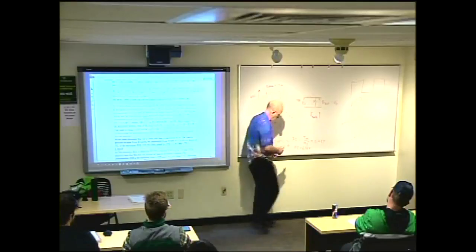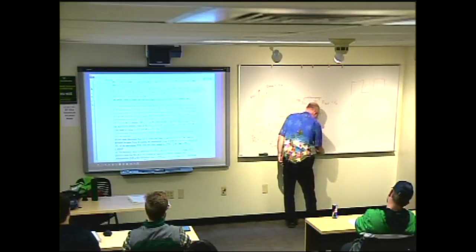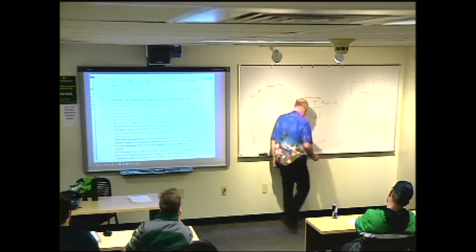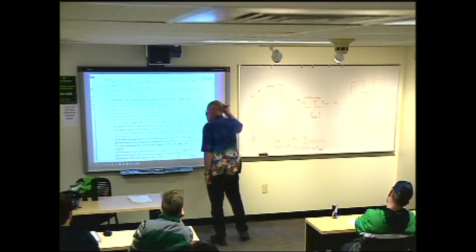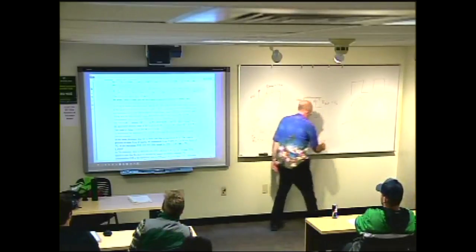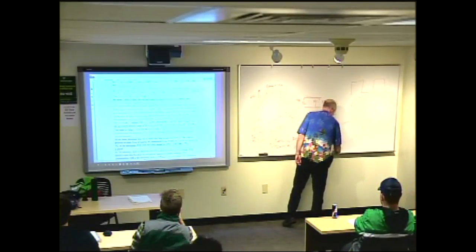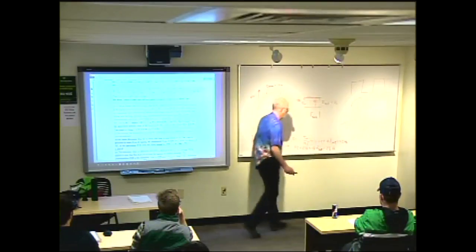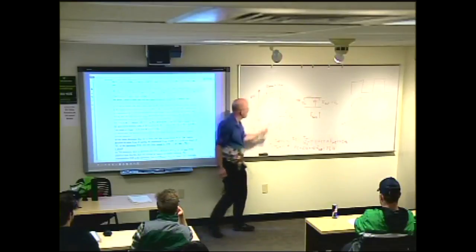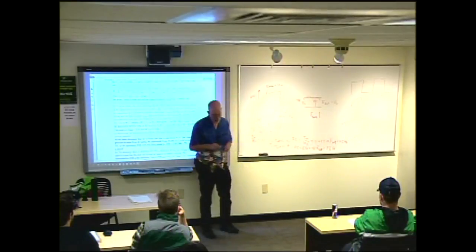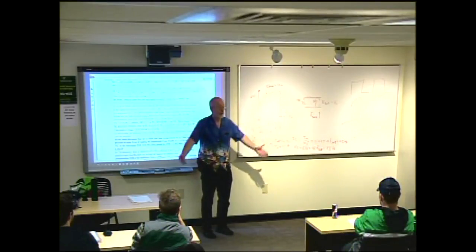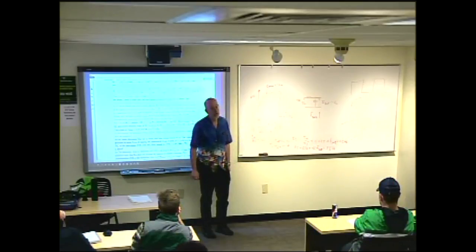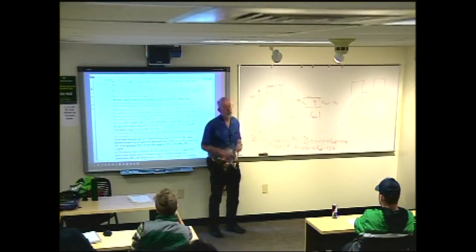Do I choose the one that's going to correspond to a 3 dB frequency of... I think this one ends up being approximately 2.5 hertz, and this one ends up being 3 dB of 12.5 hertz. Which one do I choose if I want to make sure that both of these things go through with minimal distortion? I choose the bigger one. I choose the 12.5 hertz one, so that both edges go through without being distorted.